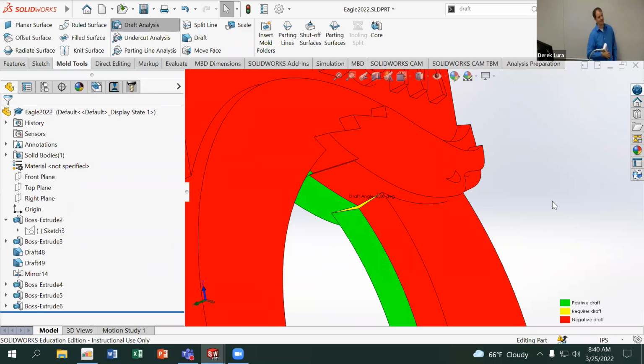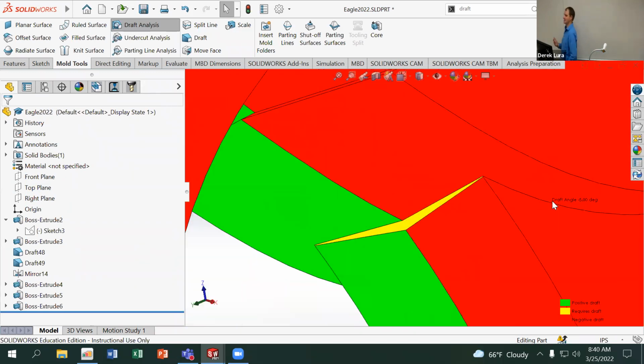It's actually flat. For this kind of one, that's a small surface. I probably don't need to worry too much about that causing the issue in my mold, right? I do have one problem with that though, is that I don't have a split going along that. I do want my mold to divide at that location. And I've done parting lines everywhere else, but you want to make sure that you have a path of edges around your entire part to use for your parting lines. So what I'm going to do is I'm actually going to split this face to make this into 2 faces.